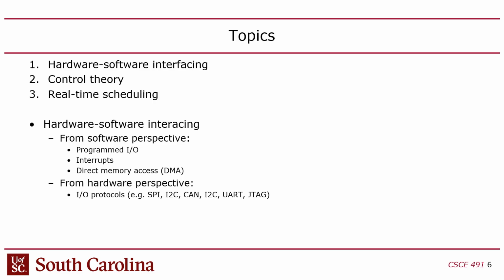Now there are some other mechanisms too, and we'll talk about them in class. There's this notion of an interrupt: because the I/O registers are completely controlled by the CPU, the CPU decides when it's going to read and when it's going to write to these I/O addresses. The peripheral doesn't have any agency, any way to tell the CPU it needs something done. So there's also this mechanism called an interrupt where the peripheral can try to get the attention of the CPU,